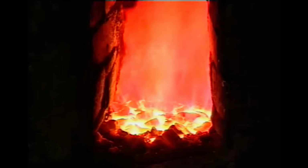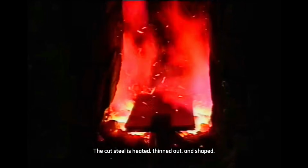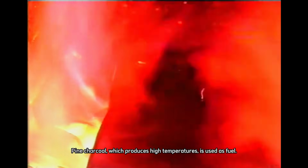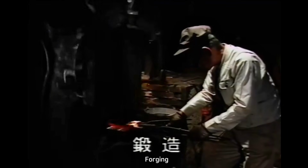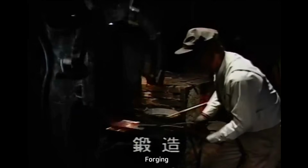Forging. The cut steel is heated, thinned out, and shaped. Pine charcoal, which produces high temperatures, is used as fuel. To retain heat, 2 to several pieces are forged at the same time.